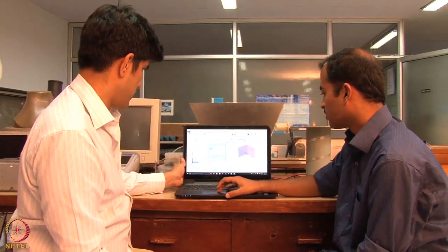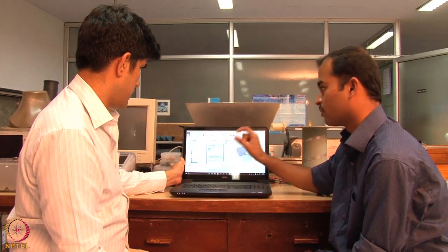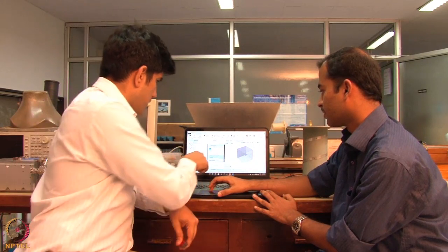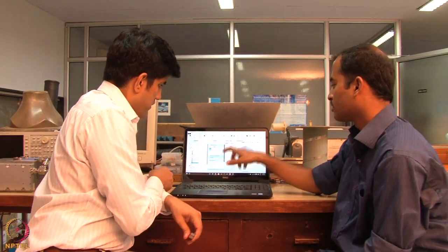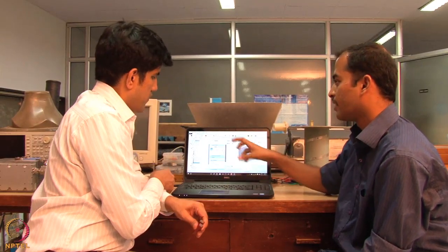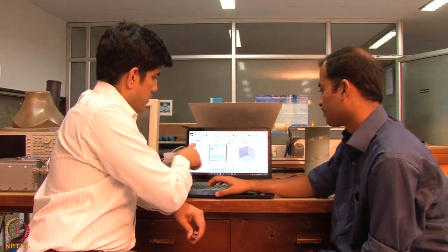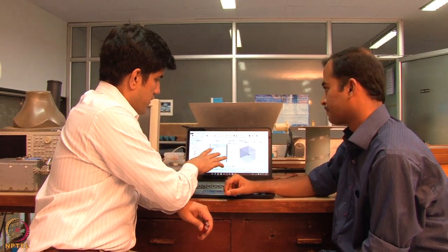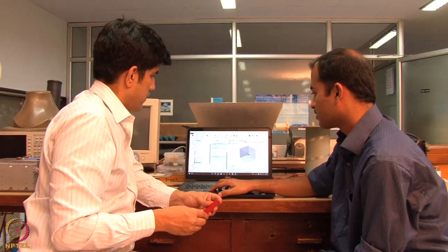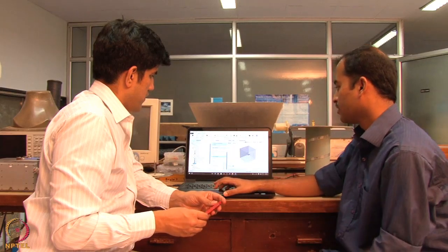Calculation. In that I have included this domain, just the iron domain. The force equation itself is the integral of a surface tensor. By integrating in that domain, we get the force in that entire domain. So this is possible within the solver, to get the value of F. These are all the settings that we have to do, and then the meshing.